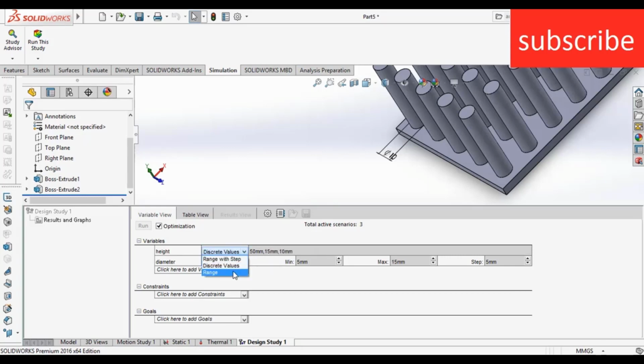Then there is range. A range is 25 to 75 mm, but there is no step, so it depends on SolidWorks how to optimize it. Remember, the main problem with range is the time consumption. It will give you a much better result, but it will consume a lot of time. So I don't prefer range. I prefer range with step.